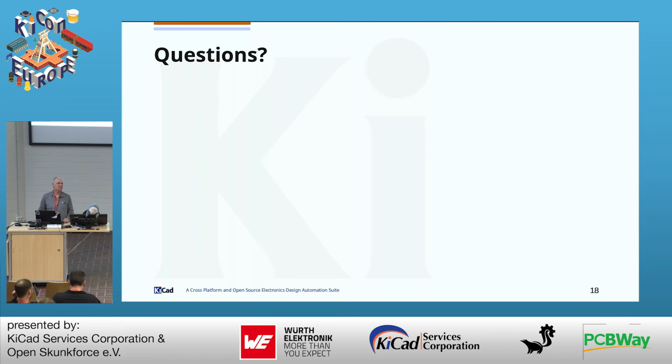Going back to database libraries, as far as I understand this, changing a resistor in a database library is a new part. It's a different part, because in the database library there is the resistor, and it has a value, and it has an MPN, and it has my internal number. So if I want to change the resistor from 1K to 12K, it's another part, if I'm correct. Well, so will this be possible with variants?